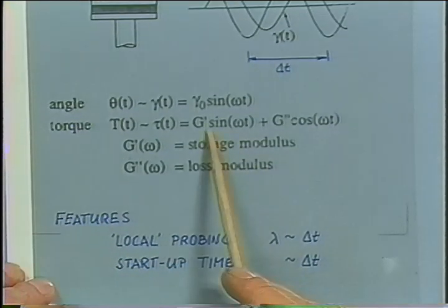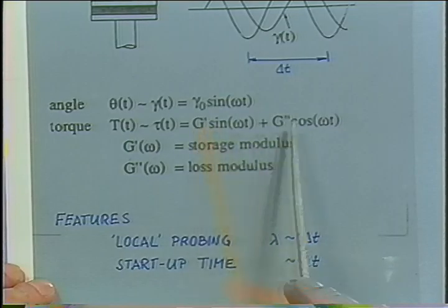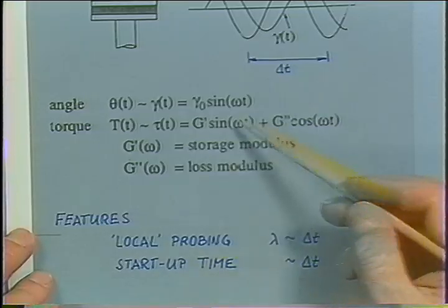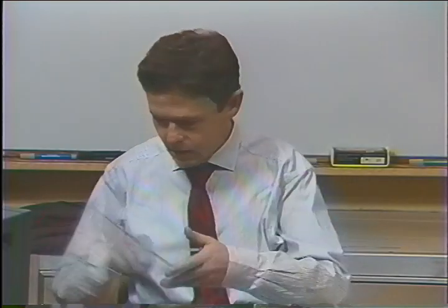Now, for viscoelastic materials, the behavior is in between, and in fact, G prime and G double prime are coupled with the so-called Kramers-Kronig relation, and we will use both of them to determine the spectrum of the material. So we should look at both functions for interesting materials. And here I have a typical fingerprint of a polymer melt.